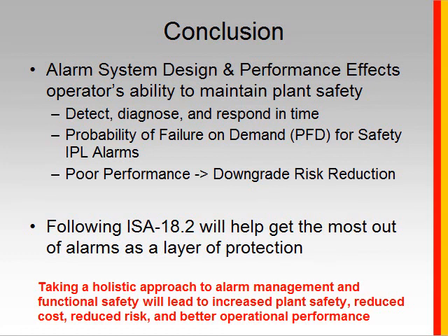If you've got poor performance, a key element of minimizing the PFD is to monitor the alarm system performance. In the event that you do have poor performance, try and fix that. And some people would go as far as to say, if you've got poor performance, then you need to consider downgrading the risk reduction provided by those safety IPL alarms.